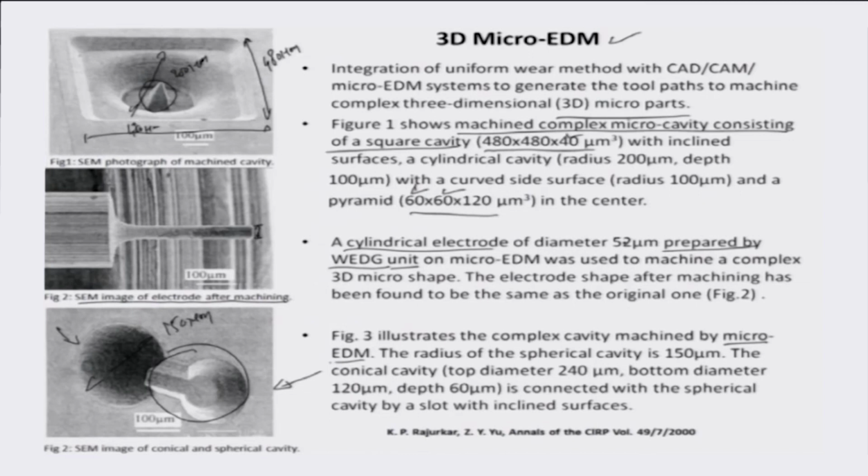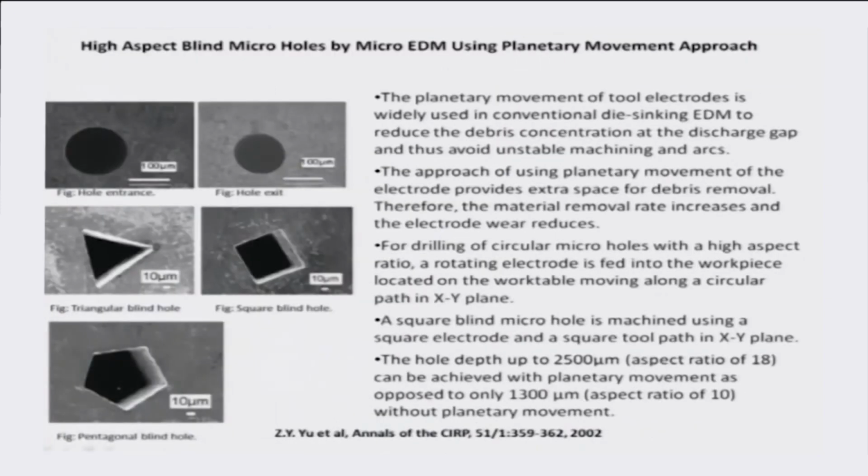So such inverted features: in one case, probably this part is made through a die sinking operation where the tool is a negative replica of this, or a cavity, and in this particular case the tool is a projection coming out of the tool surface. They can be done in parallel on a surface. So that's the capability of producing a 3-dimensional, highly structured surface at the microscopic length scale, and such operations demonstrate the capability of the micro EDM process, micro electro discharge machining process.